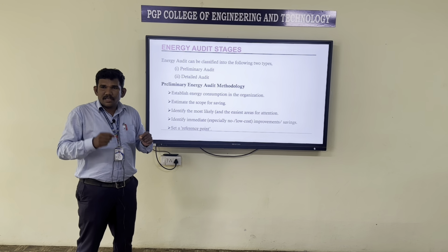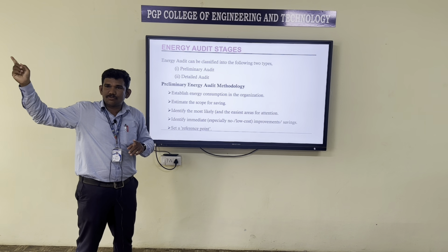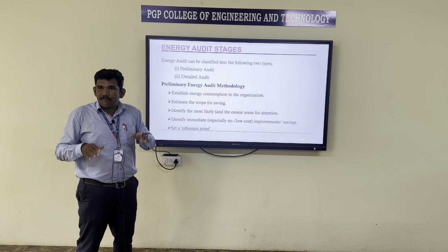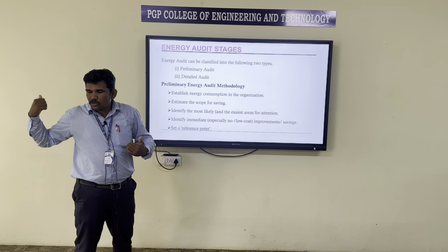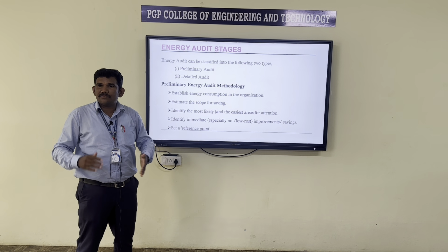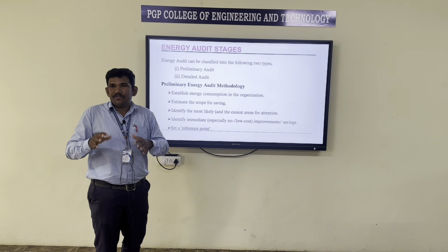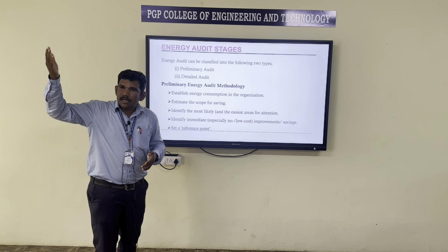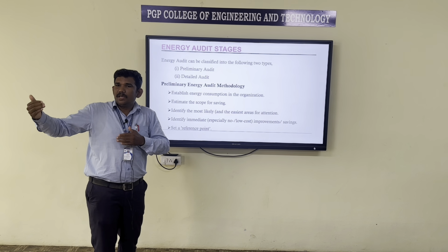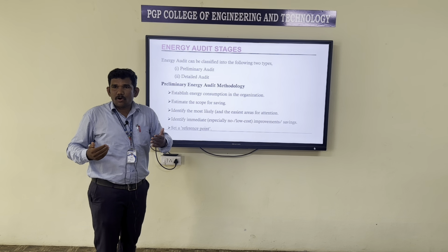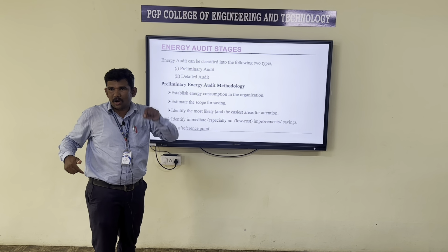Next, I will check whether the panel incoming is equal to the line I am getting from the transformer. If it is equal, no problem, the system is in balance. Once I switch on all the loads in classrooms and laboratories, the short circuit connection calculation is made. If there is any leakage, I get one input from the transformer and another input from the panel, so I can easily find out whether there is any leakage in the panel itself while connecting the load.